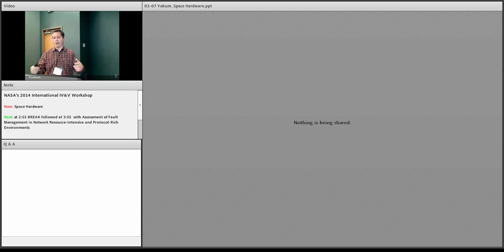And this kept happening over and over at 10 hertz until finally a higher level monitor task caught this, and it made the whole system do a cold boot, and it switched over to the other side, which is really undesirable. If it just would have interrupted, the system would have done a warm restart, and they could have captured a lot more in RAM about what would have happened during a downlink. So it was really a strange occurrence that happened.